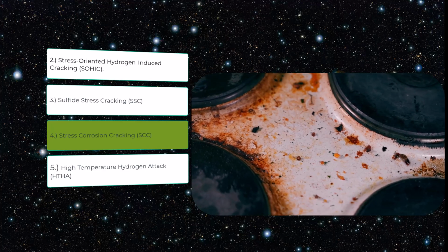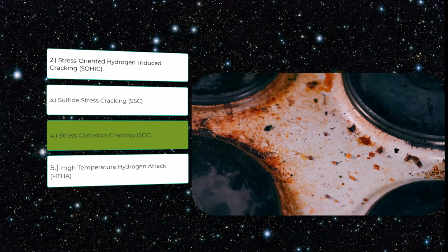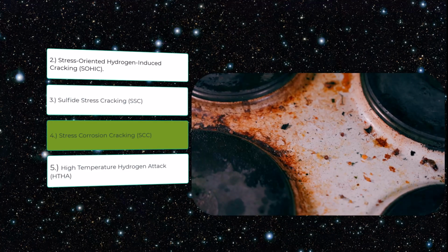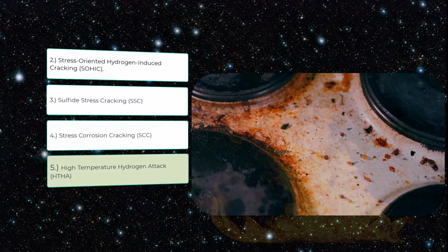Under the cap of the crevice corrosion there is a continuous pH drop due to the corrosion and the redox potential underneath that barrier, and that drop in pH causes hydrogen generation. Hydrogen can then enter directly into the steel during the crevice corrosion activity. That can result in hydrogen embrittlement.